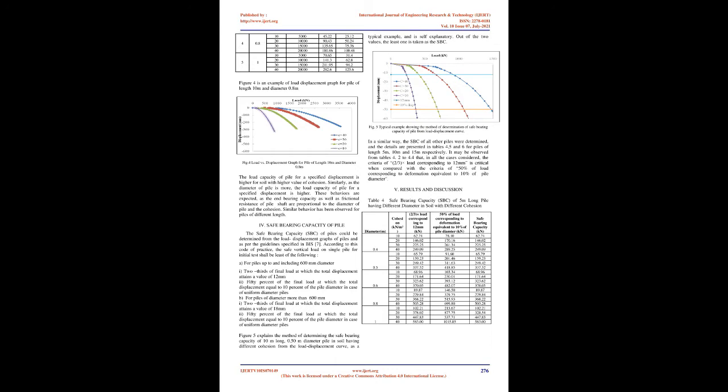Figure 3 compares the experimental load displacement behavior of piles with that obtained using PLAXIS 3D software. From Figure 3, it may be noted that, except at the initial linear elastic stage, the experimental and theoretical load displacement behavior of pile are comparable. Hence, the modeling of soil and pile using PLAXIS 3D has been validated and the same approach can be followed for further study.